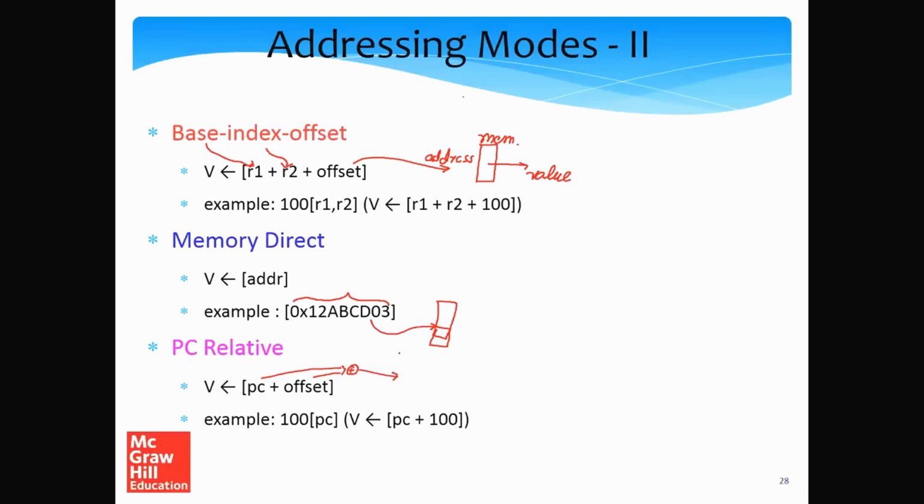Let this be the instruction memory. Then the next 4 bytes are the contents of the operand. The next 4 bytes are typically an instruction. In a 32-bit system, which we assume to be the default at least in this book, these 4 bytes from the PC will typically point to an instruction. So we will find this addressing mode very, very useful.